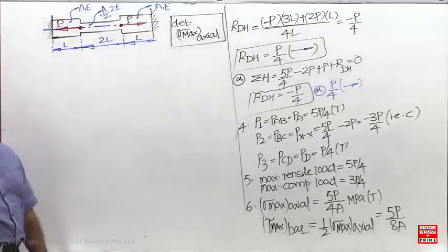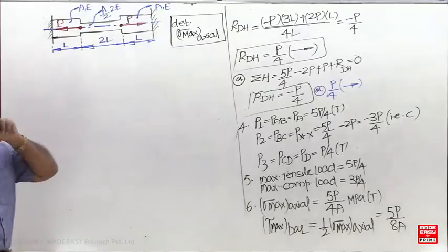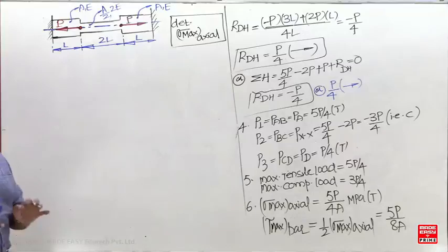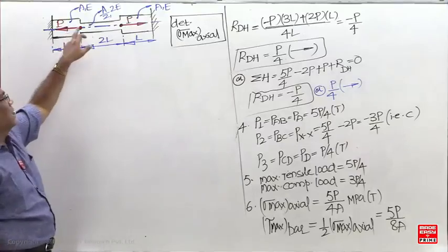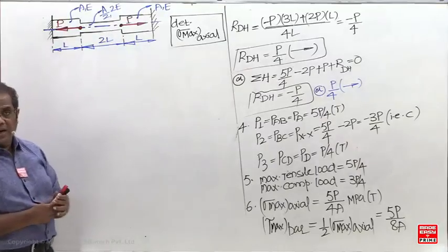Determine the maximum axial stress. Now, is your shortcut method valid or not valid? Some students are going to say not valid, sir, it is a non-prismatic bar. I have not mentioned that it is not valid for a non-prismatic bar. It is not valid when axial rigidities are unequal. Or if the axial rigidities are the same, but the axial rigidity of the first bar is AE, and it is also AE, AE, then you can use the shortcut method, it is valid.